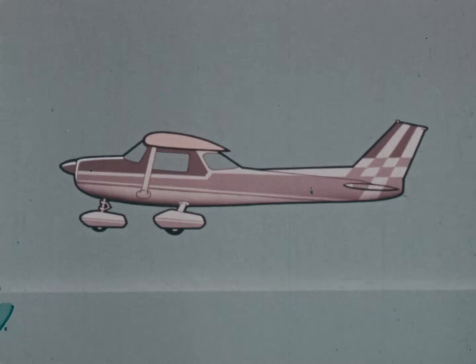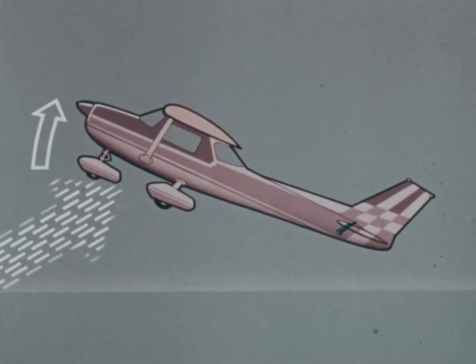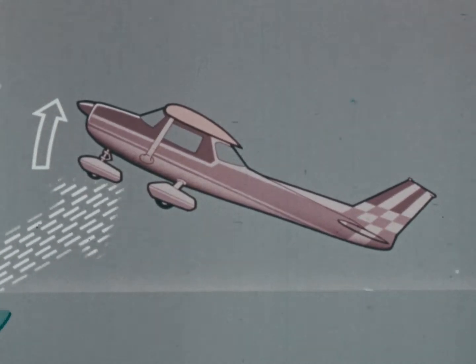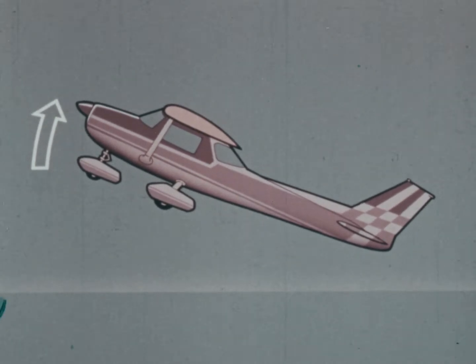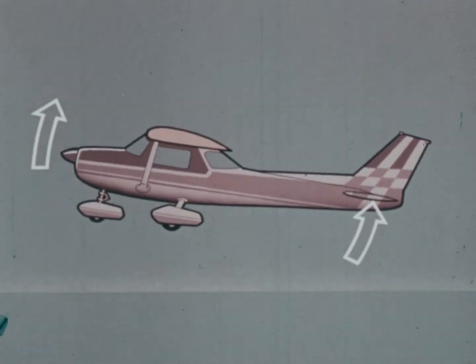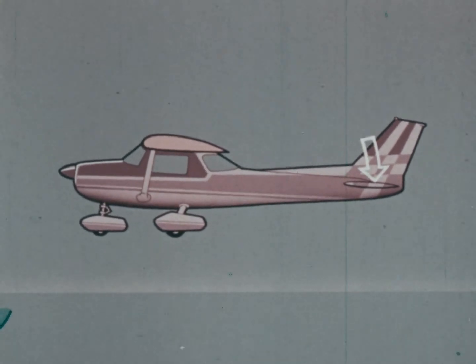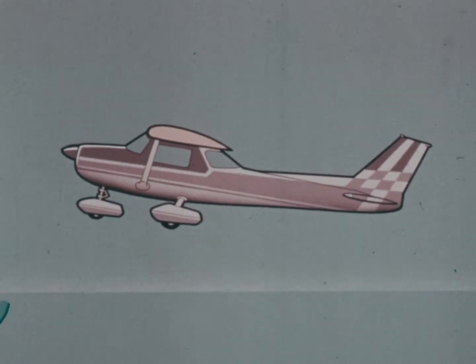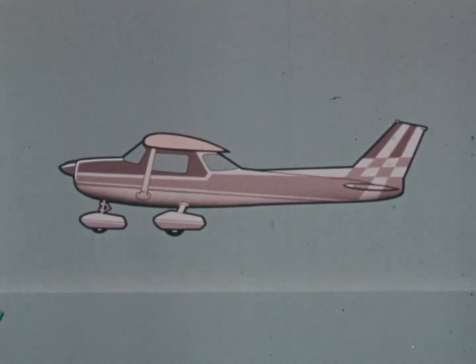When a gust causes a pitch-up moment about the lateral axis, the angle of attack increases momentarily, and so does lift. But inertia, the tendency of an object in motion to keep on going in the same direction, will prevent an immediate change in its flight path. Meanwhile, the tailplane experiences an upload, levers the tail upward, and slightly overreacts. The airplane is now slightly nose down. The tail now reacts in the opposite direction, and through several brief oscillations, damps out the disturbance, and the airplane returns to level flight.